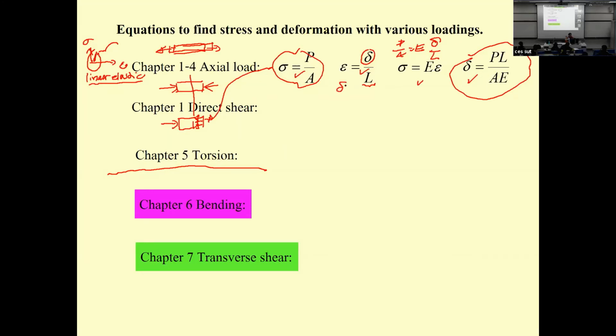If I would like to determine the elongation in the plastic region, how can we do it? Just go to the stress strain diagram, and then the stress is going to be very high, and you do the reading of the plastic strain from the diagram. When you get the plastic strain from the diagram, the equation here is going to be the plastic strain times L. This is the equation if the behavior of the structure is plastic rigid. Okay, now you guys are supposed to be very good on this already, right? You already finished reading for your midterm examination, right?